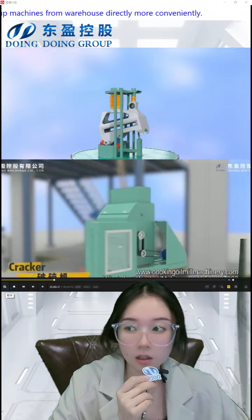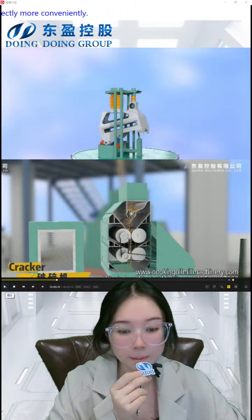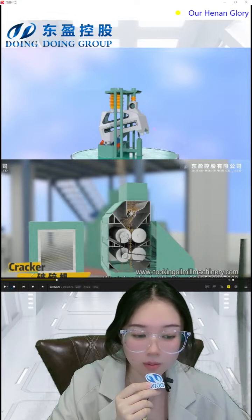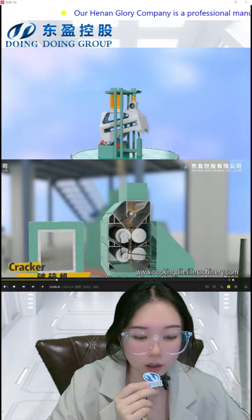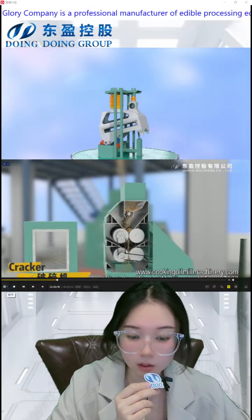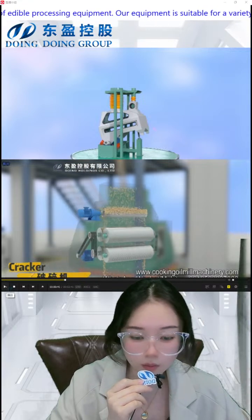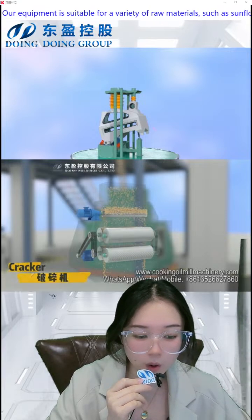The next machine is the cracker. For soybeans and peanuts, such as shells and large particle crops, will directly enter the cracker after cleaning to crush the materials to obtain small particles. The cracker can not only crush the shell, but also have a certain crushing effect on the oil seeds. After splitting the kernel and shell, the oil yield can be improved.